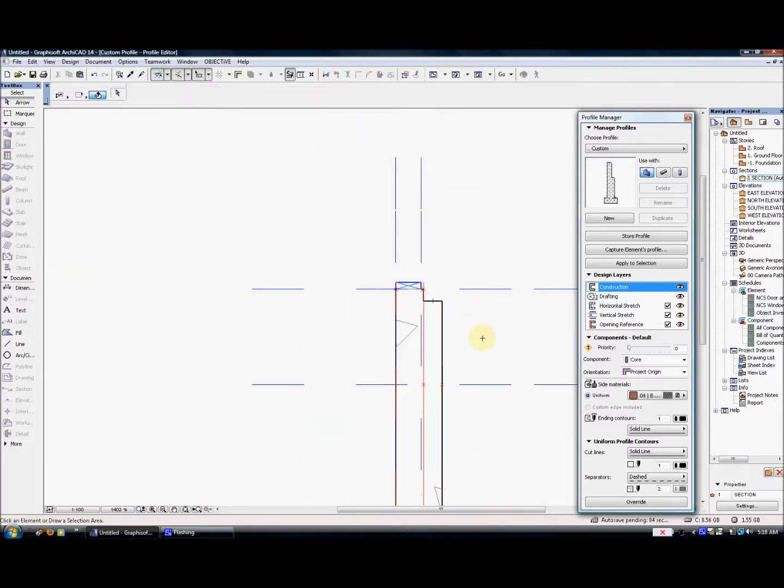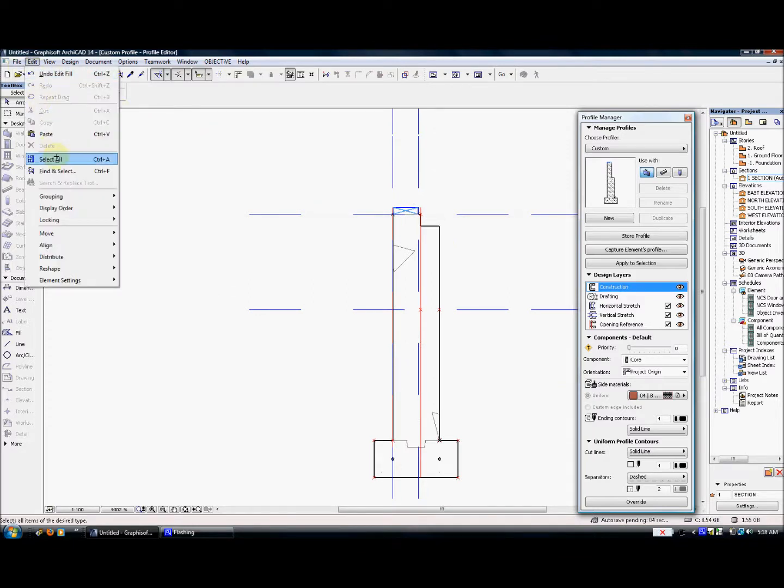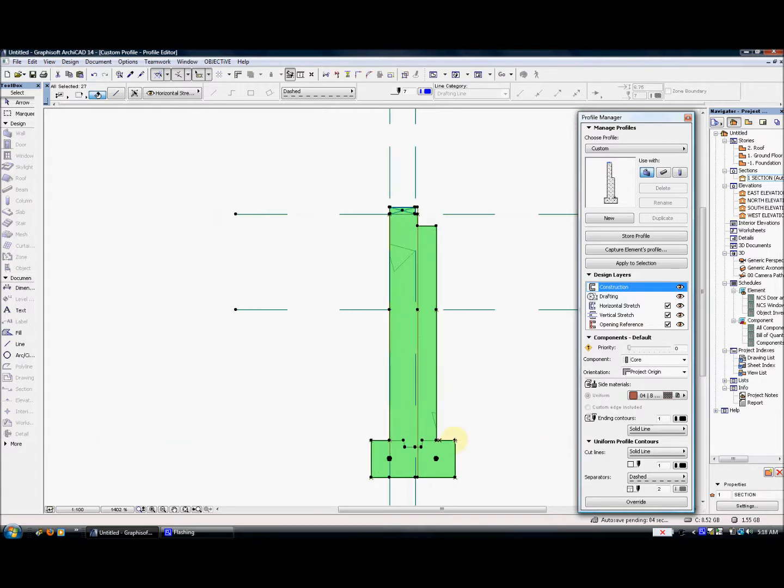The second adjustment we need to make was we need to move the entire wall in about 5/8 of an inch to line up with the wall on the first floor. So we'll go ahead and go to Edit, select All. We'll click on one of the nodes on the profile, and in the pet palette, click the drag button. We'll drag off to the left and type 5/8 inches, enter. Small move, but an important one.